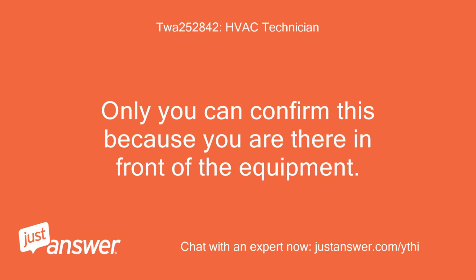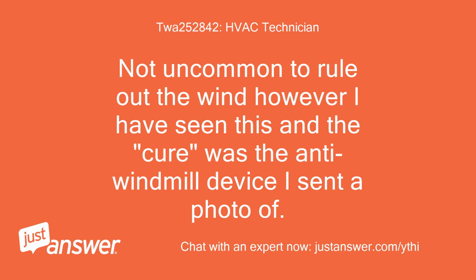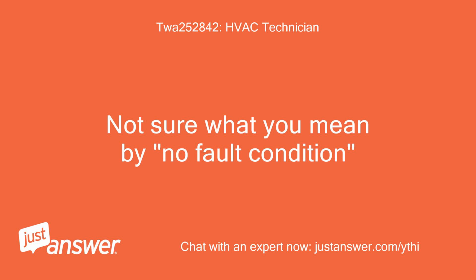Only you can confirm this because you are there in front of the equipment. No wind blowing during fault and no fault condition. Not uncommon to rule out the wind, however I have seen this, and the cure was the anti-windmill device I sent a photo of. Not sure what you mean by no fault condition.